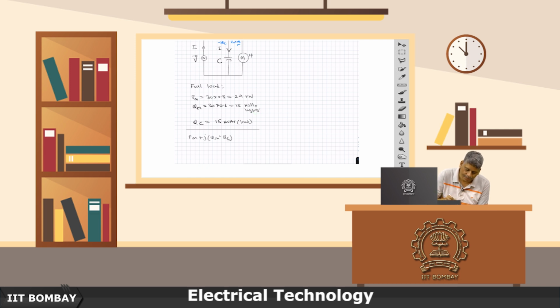So, I am going to follow the English way of writing it. If I write it as one as lag and one as lead, then the net reactive power component is the capacitive lead component subtracted from the component QM, which is lagging, and so I will get this as 24 plus J times 18 minus 15, or 24 plus J times 3.